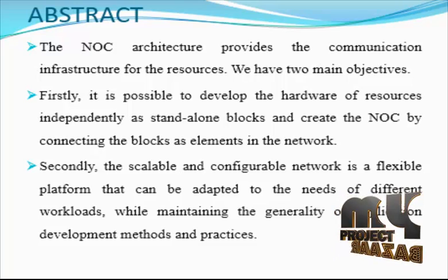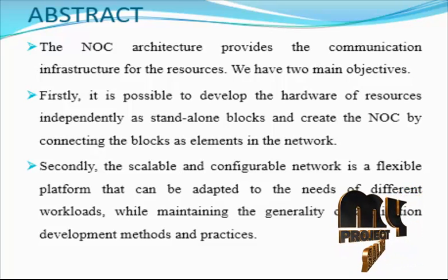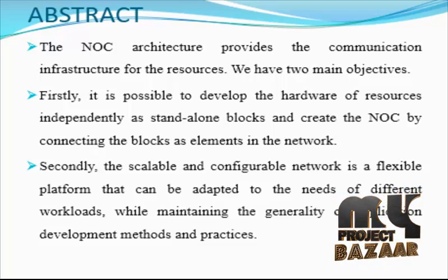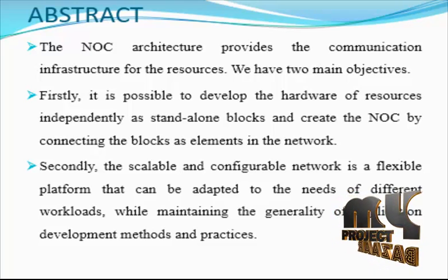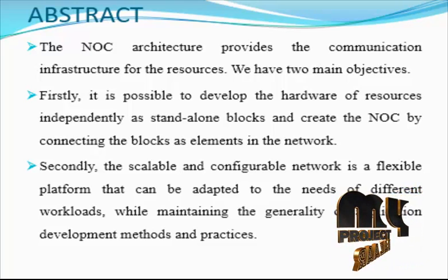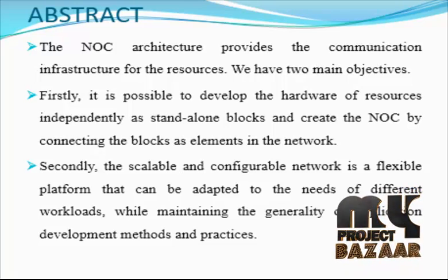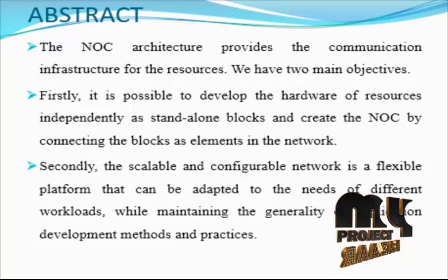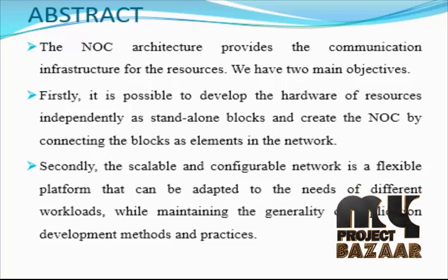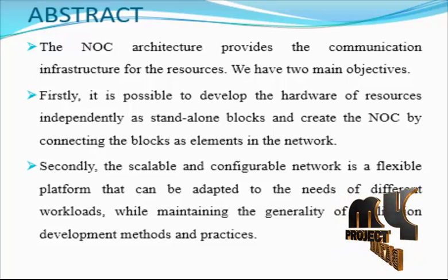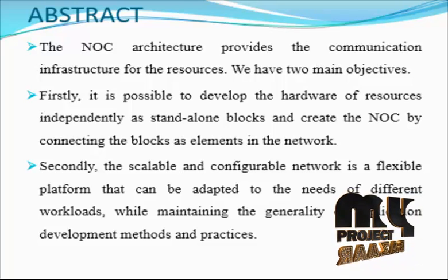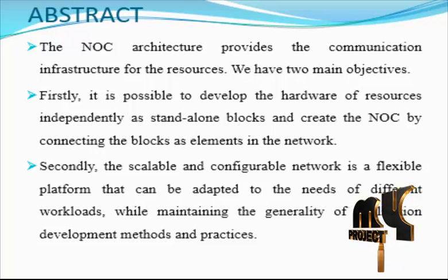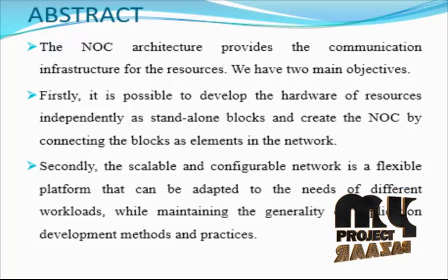A NOC is composed of a set of switches and point-to-point interconnects to form a network topology, for example mesh, tree, fat tree, torus, ring. Switches connect to neighbor switches and one or more processing elements using ports, and processing elements coordinate execution over the ports using control and data messages, either broken into packets or streamed over a communication channel.